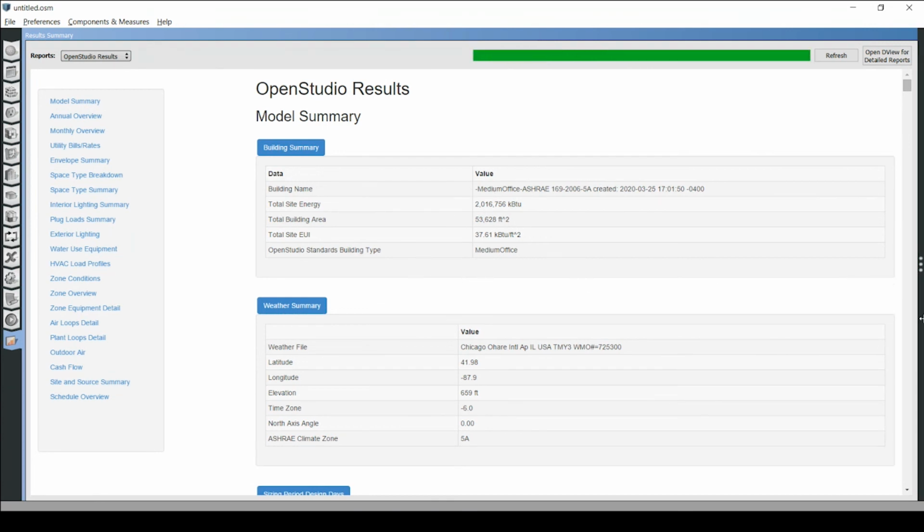Well, congratulations, you have now completed your first building energy model. Once you are more comfortable with this process, try generating other prototype models of different vintages, different climate zones, different templates, different sectors and types. And try adding more detail to your model. Try replacing other parameters in your model, such as chiller efficiencies, people densities, occupancy schedules, and whatnot. And try applying additional measures and creating your own building geometry.